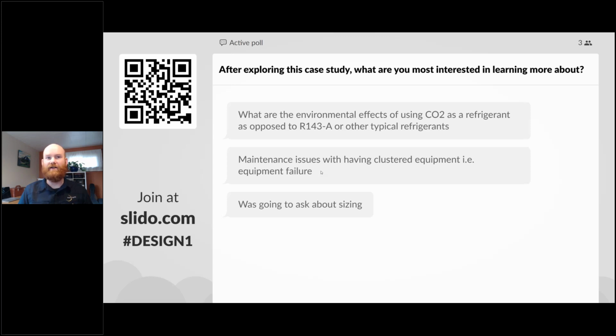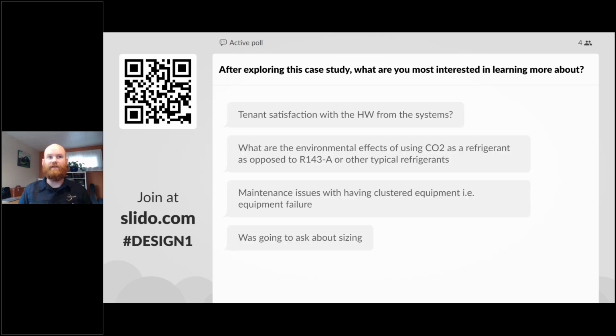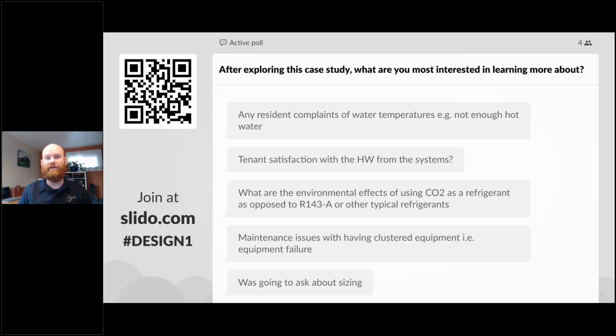But the first cost savings were substantial enough, as well as how the system was laid out on the rooftop, really tried to minimize those maintenance procedures and tasks and make it very easy for them to be done. One of the things we have with maintaining heat pumps is cleaning air filters. And so we wanted that heat pump on the roof to be easily accessible, not on a penthouse roof, so that the air filters could be easily cleaned on a quarterly basis by the maintenance personnel.